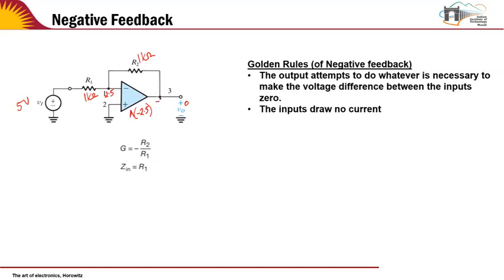So now it becomes a negative number. Let's say this goes to some minus saturation value. And therefore, once I've got, say, minus 10 volts over here, then minus 10 will drop across this resistor path R1, R2. So I have 5 volts here, minus 10 here. So this can turn out to be something like minus 7.5. So essentially what was a positive number is now getting subtracted, and this process can go on iteratively until the system saturates. And that's how this process of feedback is working. So whenever I have an input which is large, the output will try to suppress that input.